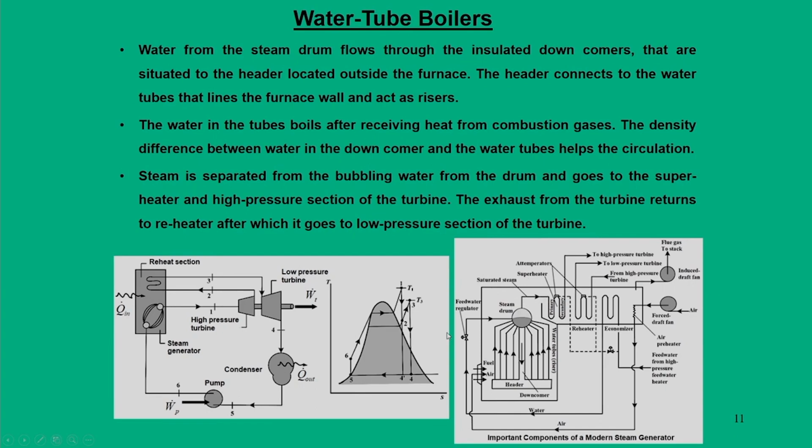So, essentially we are coming from this path, and if some reheating is required, then we have a reheater unit. Reheating means that once you have reached superheated steam and the first expansion takes place in the turbine, then you are reheating from 2 to 3. That reheating comes from the reheater, and again it is also part of the complete steam generator.